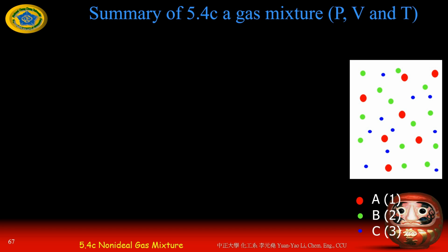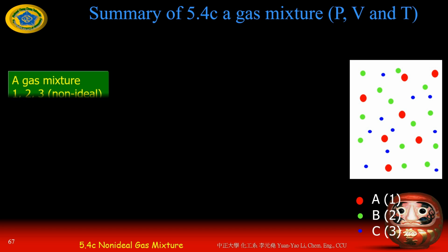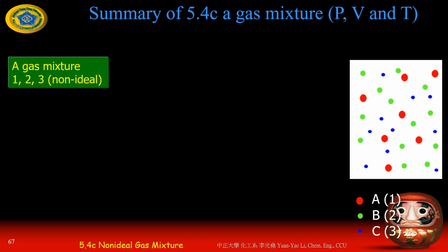As usual, let's have a quick recap about what we have learned last week. Last week we talked about the pressure, volume, and temperature relations with the gas mixtures. Especially, we want to know how to use Kay's rule to find out the pressure, volume, or temperature.